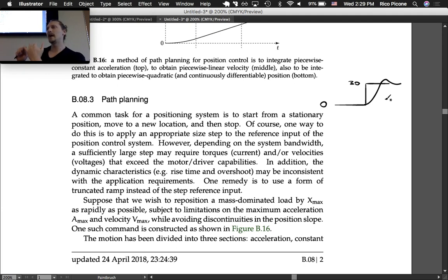But if you have that be the case, then when you were designing your controller for a specific rise time and settling time and all that, if in your simulation you didn't take into account that saturation, then the actual performance won't be the same. You can take into account the saturation of your control effort in your simulation, but it's harder to do that.